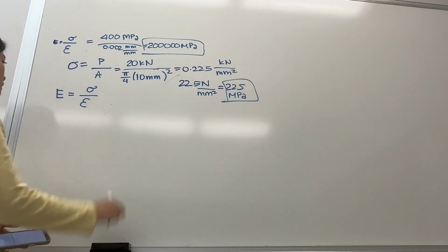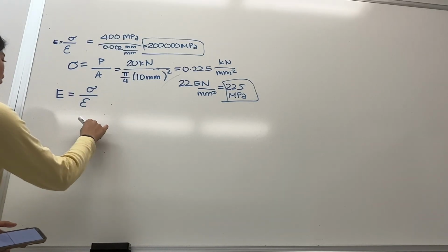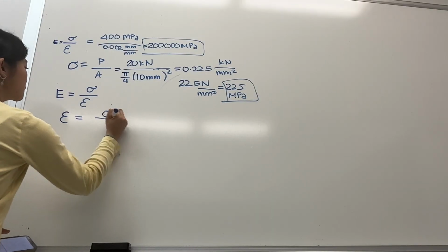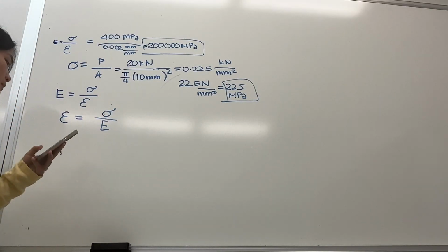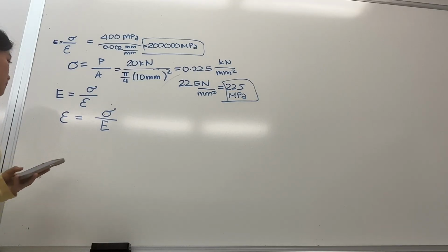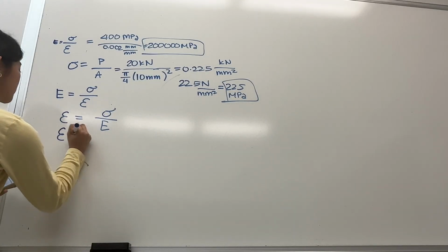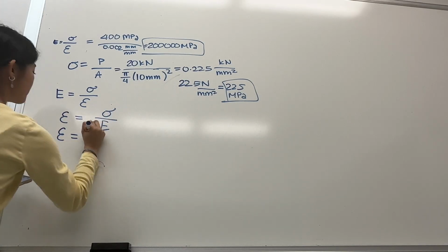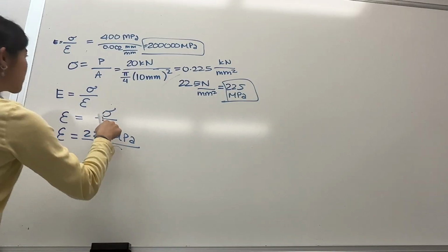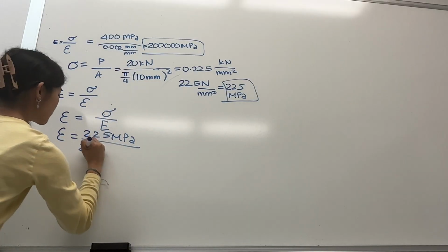Strain equals stress over our modulus of elasticity, so 225 megapascals over 200,000 megapascals.